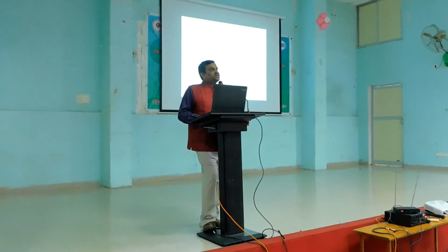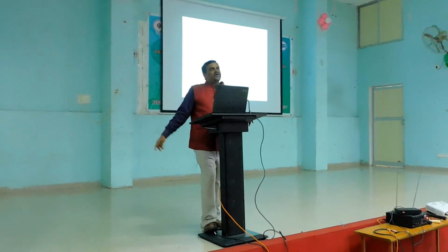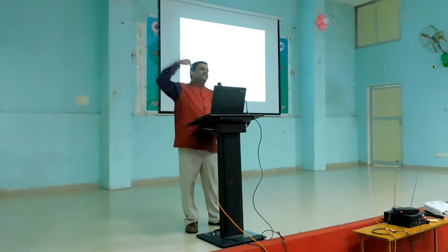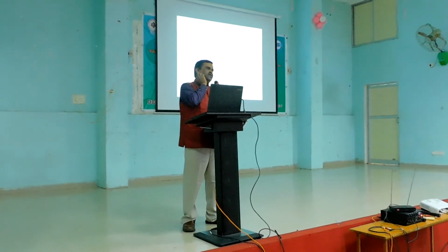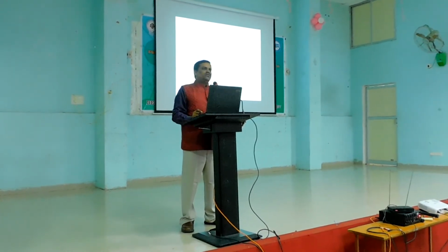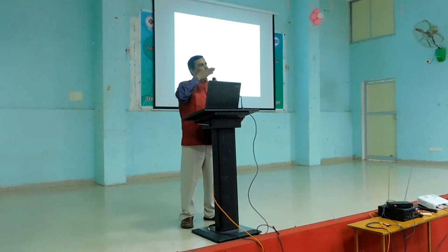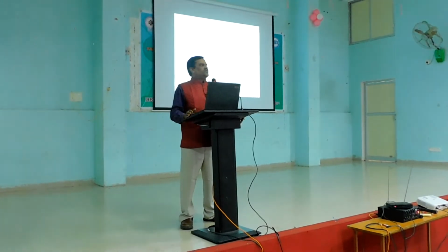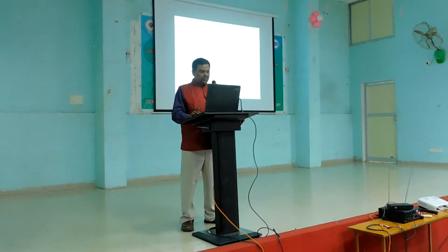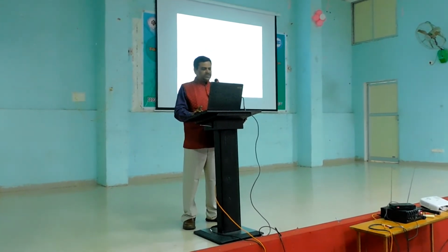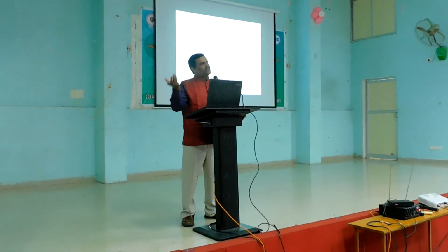It is an exponential variation. From one end to the other end, the Young's modulus is tremendously increasing because of this nano reinforcement. By incorporating a nanomaterial continuously, you are tuning the properties; the material properties are not at all the same for the entire material. That type of non-homogeneity, aspect ratio, modulus ratio, you can continuously monitor, and such a material you can use in different applications.